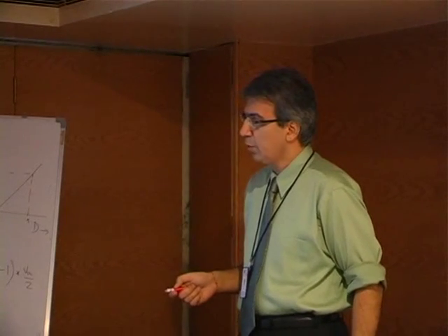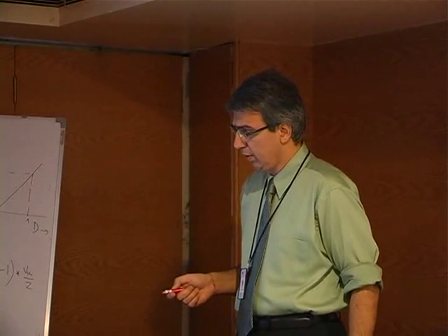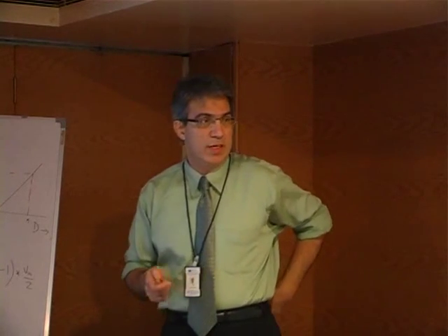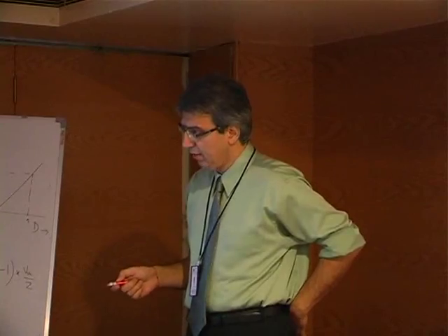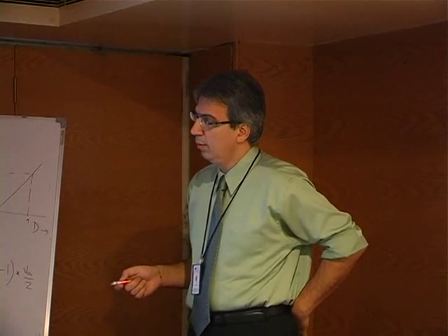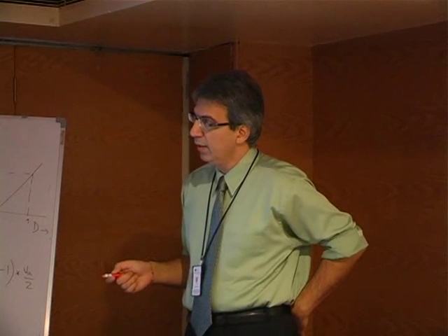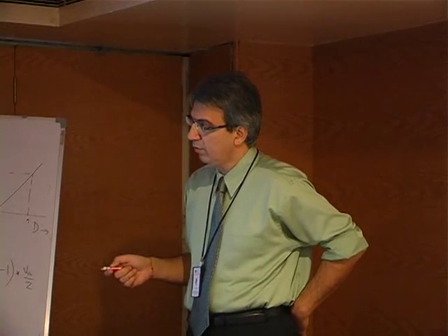MF should be as large as possible. Of course, if you are doing a very high power drive using IGBTs, you may not be able to have a very high frequency of switching. But if you try to have very high MF, then this becomes less of an issue.